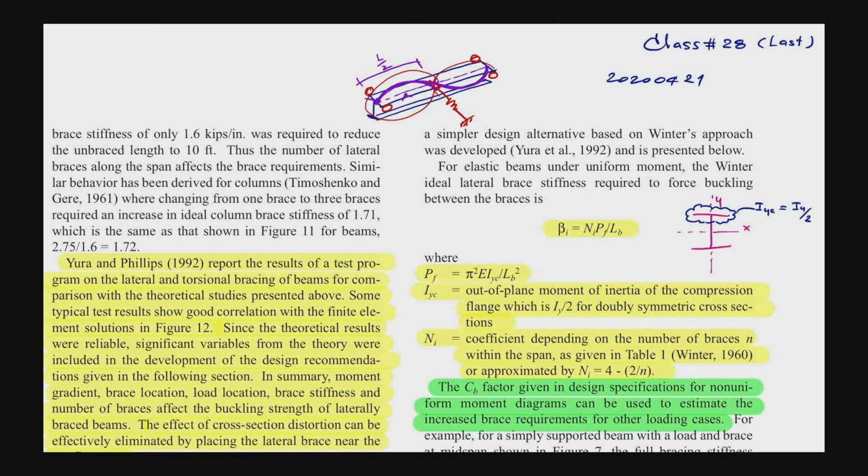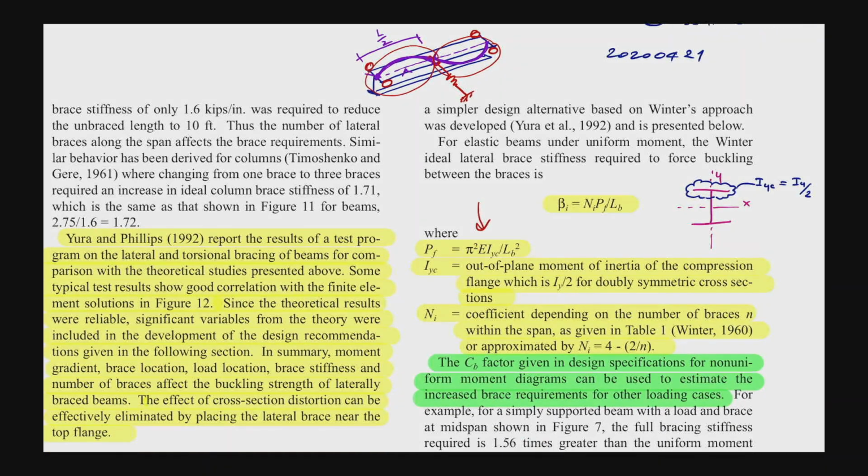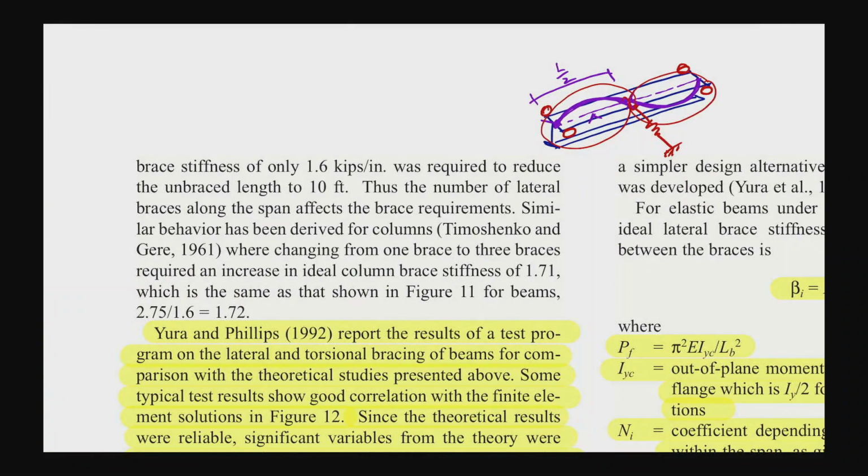So elastic buckling, first of all, this is the elastic buckling of the column. If you recall, the elastic buckling part is there, and the inelastic buckling part is going to be another part there. And elastic buckling just goes up. This is going to be really high, right? So this could be crazy in some situations. So Pf equals pi squared EI over L squared could be ridiculously unrealistic, because the beam might go into inelastic buckling.